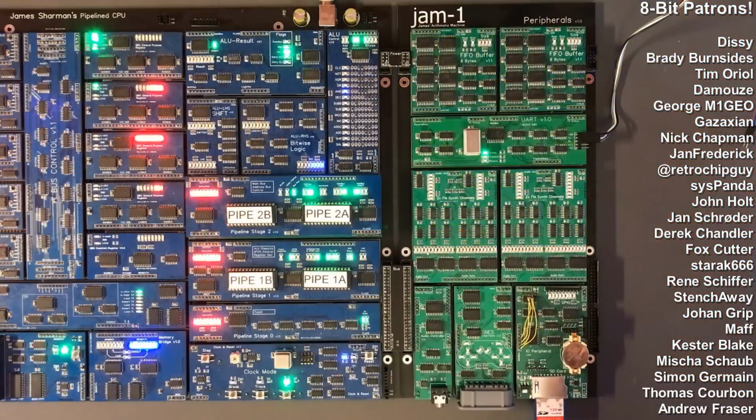Hardware flow control would let us continue to do that because it would allow the system to throttle to whatever the send rate was. I could switch it from 4 MHz to an interactive clock frequency where you can see the interactions of the internal parts. And so the addition of hardware flow control would allow me to still have that interactive experience and demonstration ability for the system, but without needing to worry about the UART overfilling its buffer.